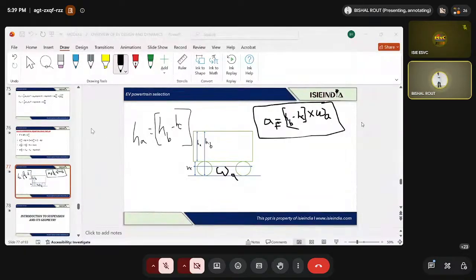And you can see over here, there is 1 upon radius, and 1 upon 0.31 has been given as an input. This particular block is actually telling you the hill climbing force, right? You can see this is a gain which has been multiplied. Currently, let us suppose I am taking the theta angle to be 0. If theta angle is 0, sine theta will be 0, so there will be no impact of this. If there is some angle in between, definitely the impact will be different, right?